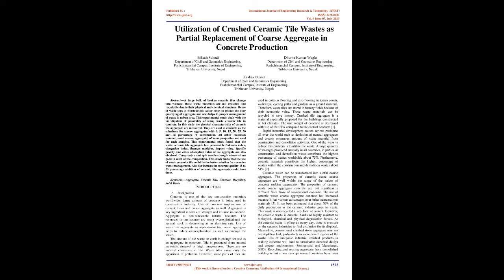This study finds that the use of waste ceramic tile could be the better solution for ceramic waste management. Also, for an increase in concrete quality, 15 to 25% addition of ceramic tile aggregate could be done. Keywords: aggregate, ceramic tile, concrete, recycling, solid waste.